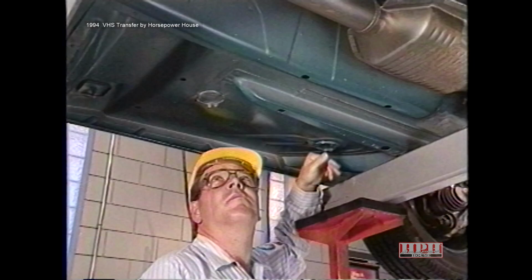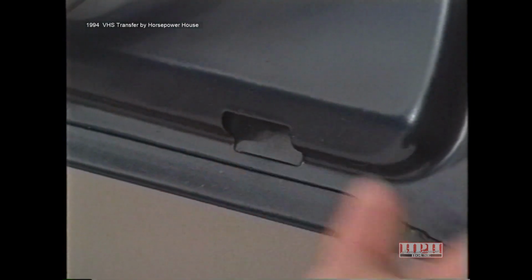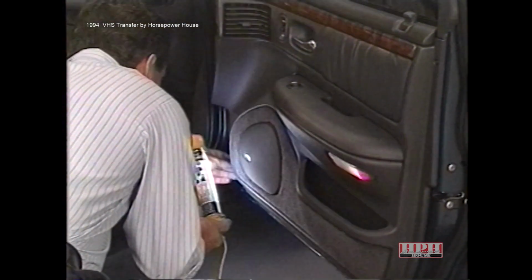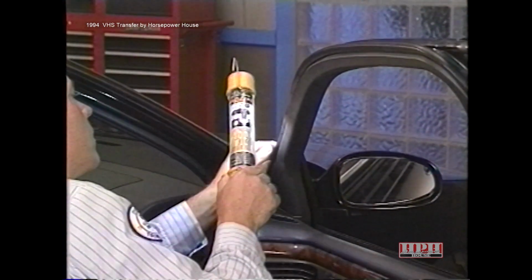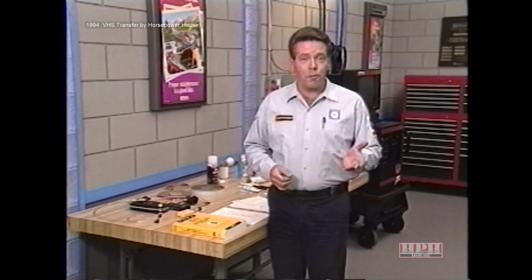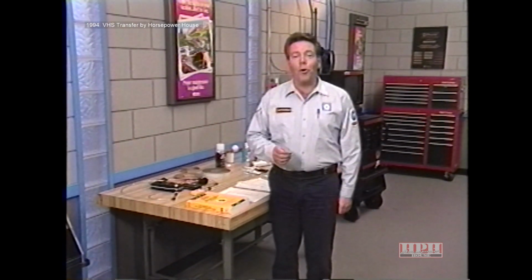When a water leak is the problem, check for missing floor or body plugs and be sure all drain holes are clear. Also inspect for proper sealing at windows, doors, and body seams. And look for body component misalignment. A mirror or bright light may be useful when trying to inspect difficult-to-see areas. Many of the problems you find during a visual inspection can be corrected by simply repositioning, gluing, or adjusting an existing component. And remember, don't be misled by the